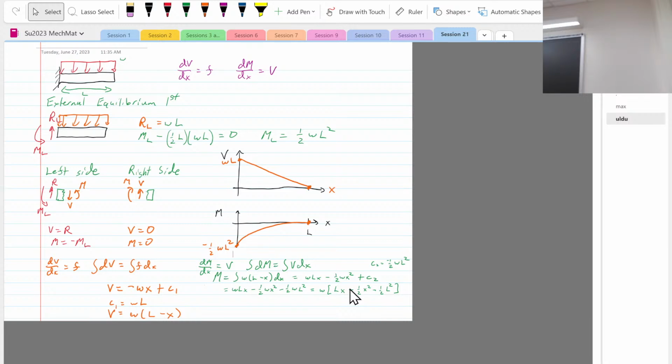So what you have to do is go through all that, and then you probably won't have a problem with these diagrams directly. We're typically dealing with 2.5D problems, so you're going to have a sigma x, a sigma y, and a tau xy, or you have a sigma y, a sigma z, and a tau yz. We're drawing a planar diagram for in-plane stresses, then we're going to go about doing the Mohr circle.